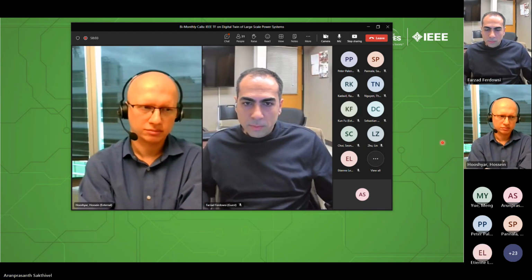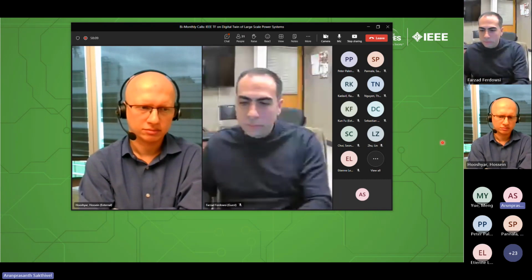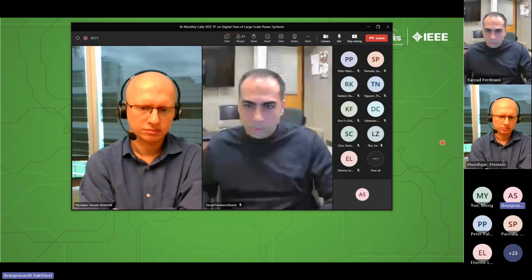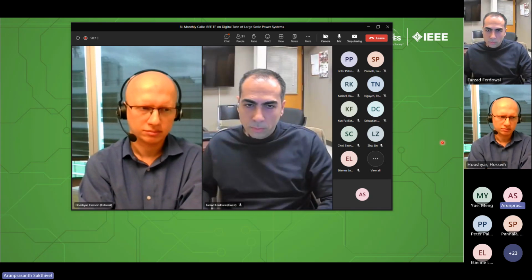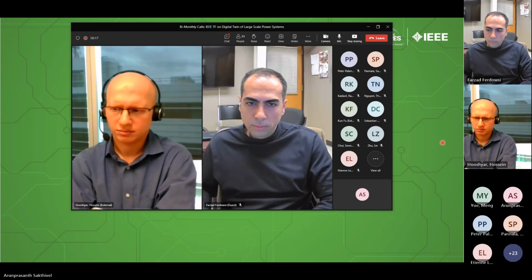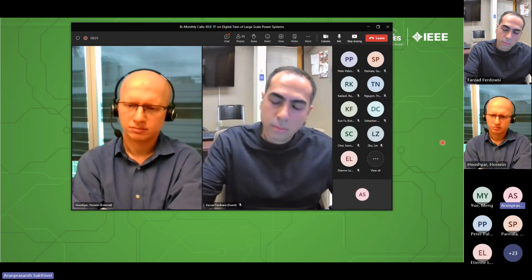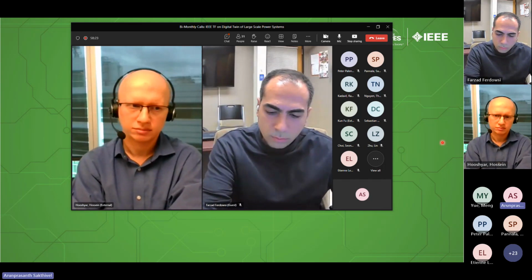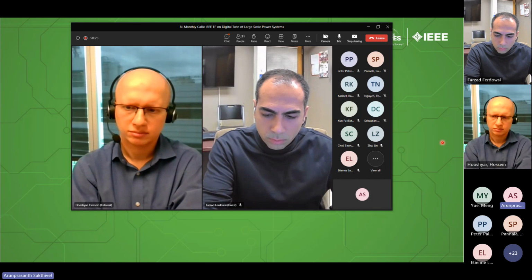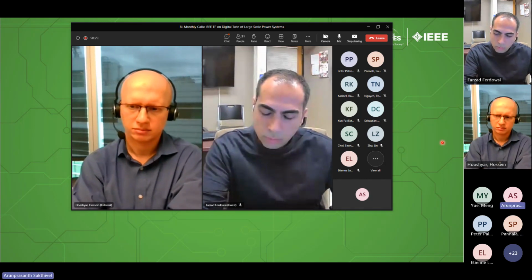Okay, thanks for the question. As far as I think, mostly utility people will start from their transmission network. So at least they want to model the majority of the transmission network, because losing a transmission network is more critical than losing a distribution. So based on my understanding, generation and transmission is what we need to model. The distribution can be equivalenced.